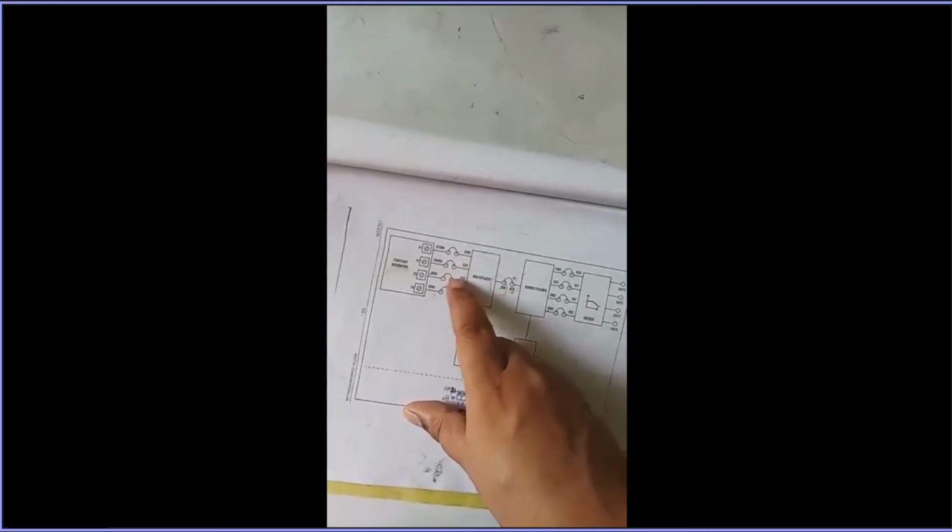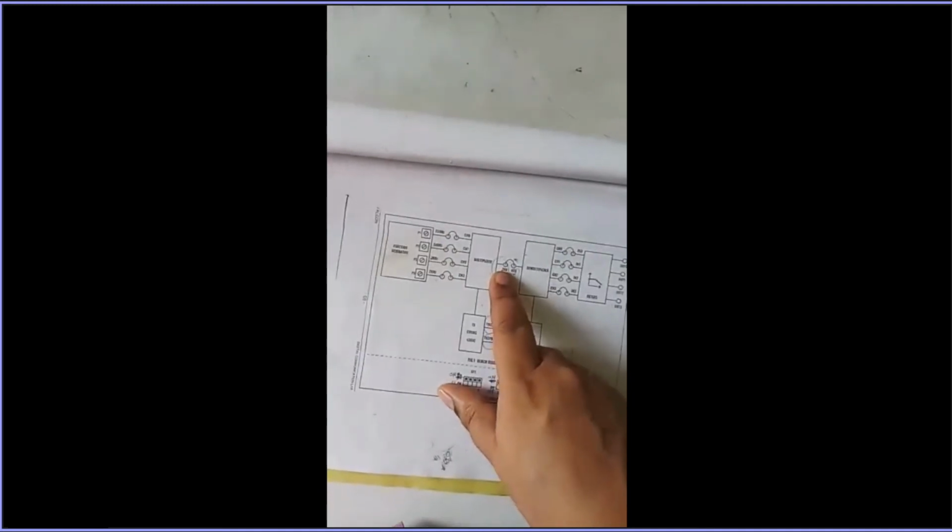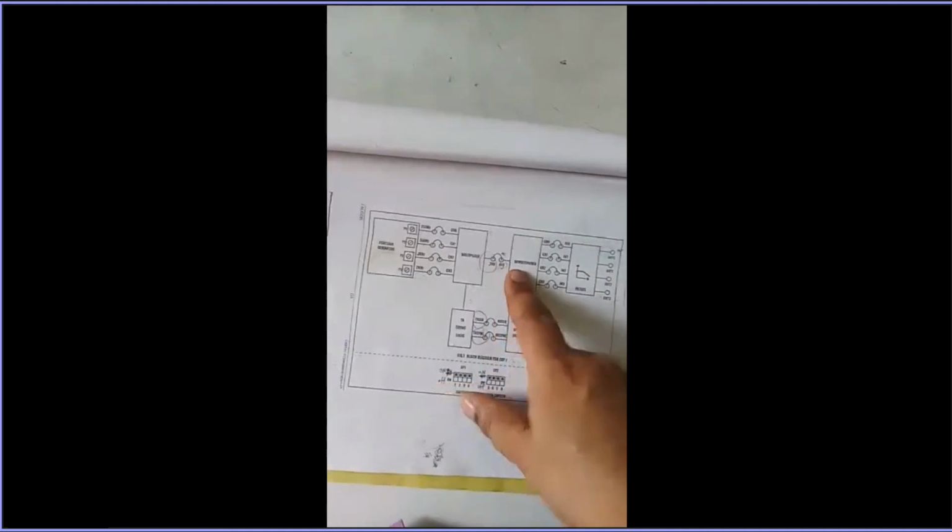This is the block diagram we are going to use for the experiment. You can see that we have the function generator and we have 4 lines, 1, 2, 3, 4. We can use the same frequency also, but here in the lab we have options. So we are providing different frequencies, 250 Hertz, 500 Hertz, 1 kilohertz and 2 kilohertz. Those signals are provided to this multiplexer. Then the combined signal will go from the multiplexer to the demultiplexer.